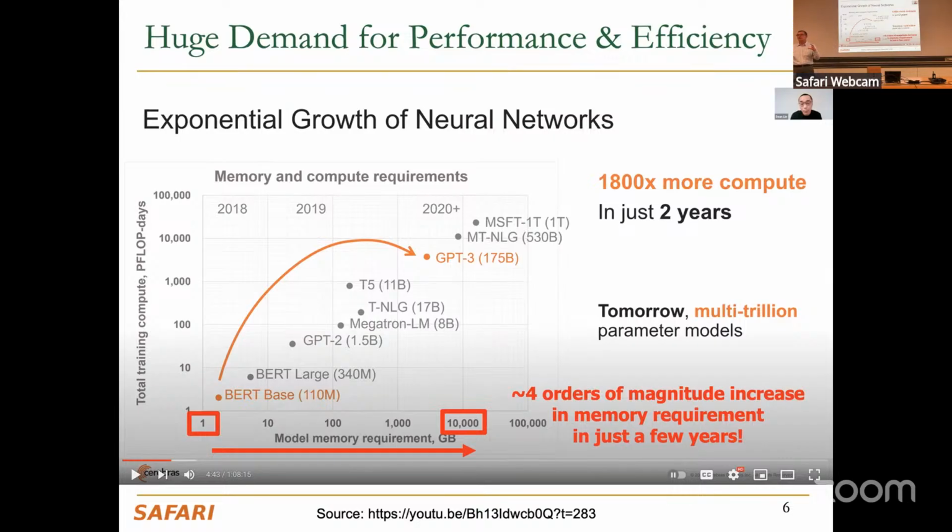Now, the problem is if you actually design a wafer scale processor, and if you don't design the memory right, you may not have a lot of memory on that chip. And these folks can easily put a lot of SRAM on the chip, but SRAM, as you know from DDCA probably, is not a dense memory technology. It requires 6 transistors, right, in the best case. And that's very expensive. And as a result, the amount of memory that they put in this wafer scale chip is 40 plus gigabytes, which is very small, right? Maybe they went to 80 at some point, but again, 80, 40, it's very small memory. We should really have memory on the order of terabytes and terabytes for large-scale applications. Okay, that's good to think about.